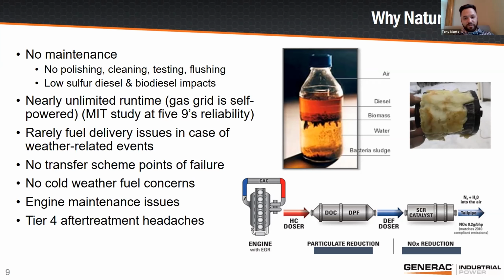And there are multiple points of failure in this kind of after treatment system, just to use your generator outside of an emergency standby event. If you ever wanted to monetize or get a payback on your generator, you have to have this very complex diesel after treatment to do so. With natural gas or propane, especially the ones that Generac sells, we use different technology that doesn't require all of that after treatment. And we'll talk a little more about those benefits in the next two slides here.